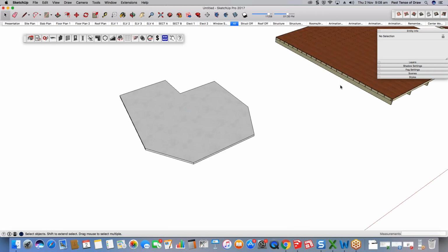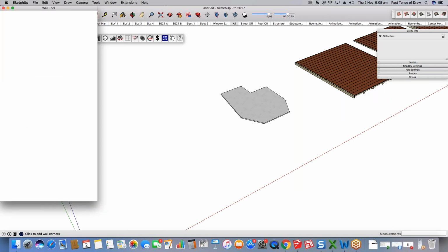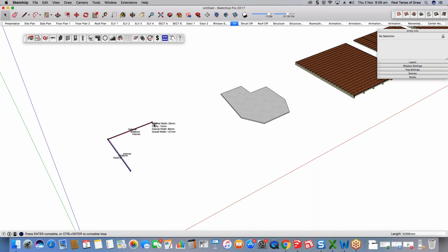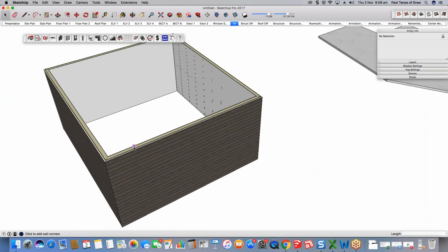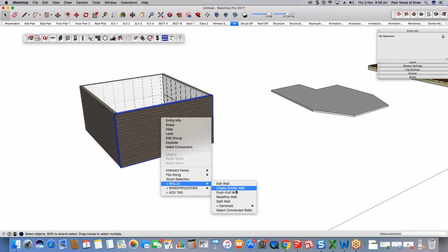That might be new to many of you, because as you would know, when you're drawing with the PlusSpec wall tools, if they form a loop and are all joined, it means that you can one-click generate items. So I'll quickly draw another shape to demonstrate it. Once you join your loop, you can right-click, walls, generate, and then you can say roof from walls, but you can even do face at base of walls and face at top of walls.